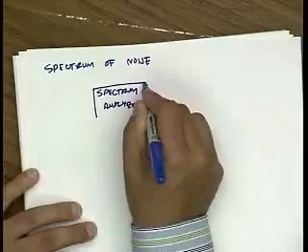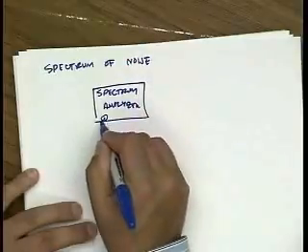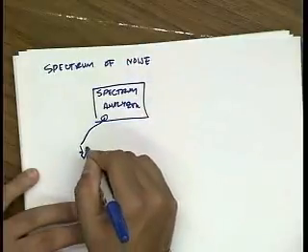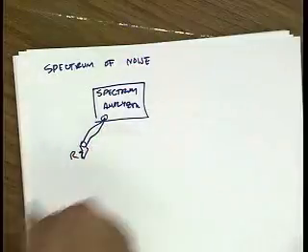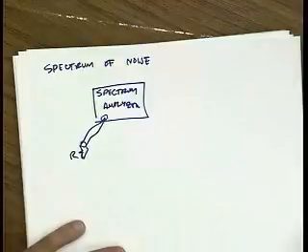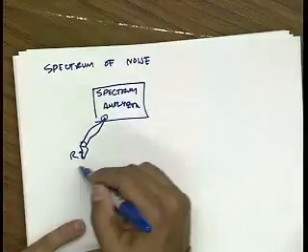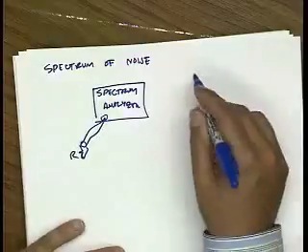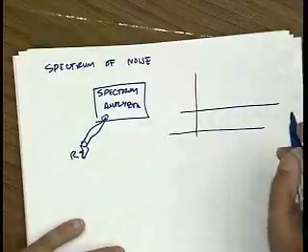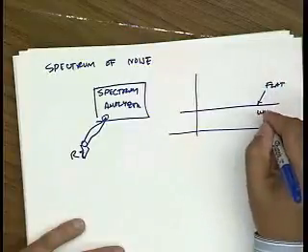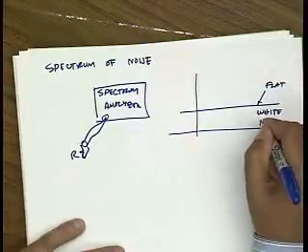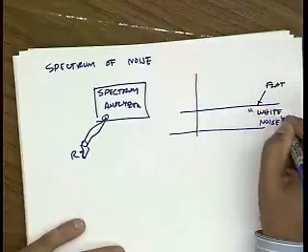Remember, we talked about this briefly last lecture. So this is the cable hookup. I take a resistor here, R, I just hook it up to my spectrum analyzer, and I look to see what kind of spectrum this resistor noise has. What I find is that it's flat, or what we call white noise. And this is true for most resistors, okay?